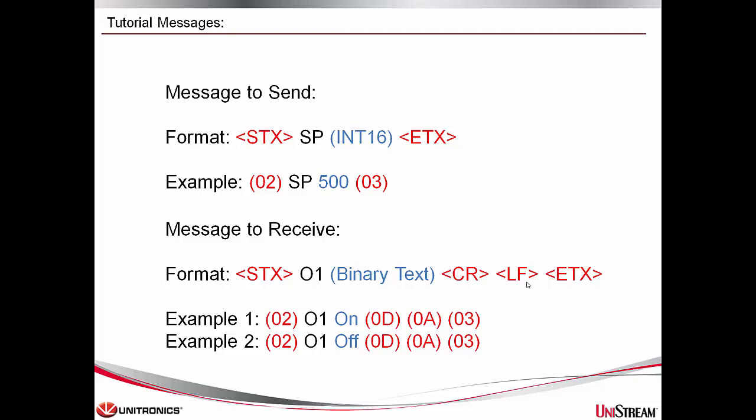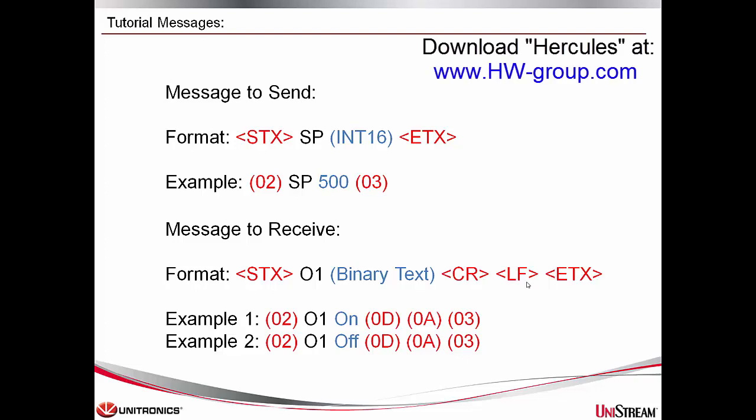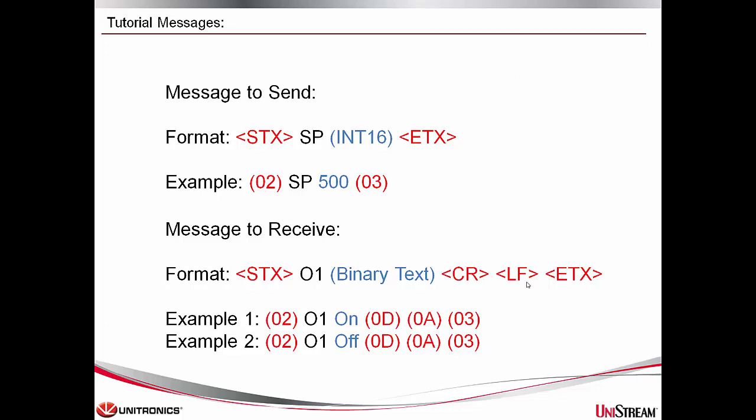In order to test these messages, a PC-based utility program, Hercules, will be used to both receive messages from the UniStream and send them back. The PC and the UniStream will be connected using a serial connection. Next, we can start building the project in UniLogic.